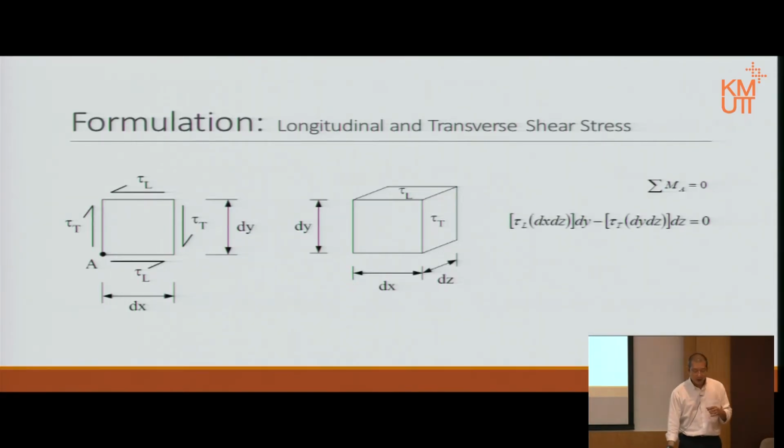Now, the first term is the moment caused by that stress. That stress times the area, which is dx and dz, dx dz is the force. And then times the arm dy, it becomes a moment about point A, and of course it rotates anti-clockwise.